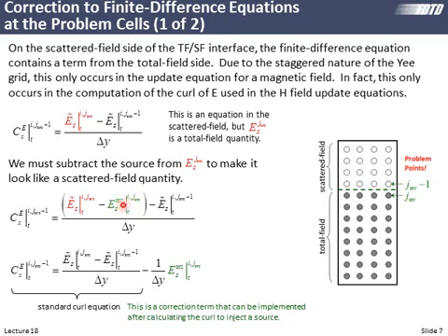Well, we can factor this correction term out to the outside, and what we're left with is the original curl equation minus a correction term that only has to happen at this one plane. The rest of the curl term we calculate everywhere on the grid. So what kind of cool happens is this tells us we can calculate the curl across the entire grid just like we've been doing, without knowing or considering anything about this total field scatter field source. When we're done the loop calculating the curl, we can set up a loop to just go horizontally across the grid, just across this one row, and subtract these correction terms all the way across the grid after we calculate curl.